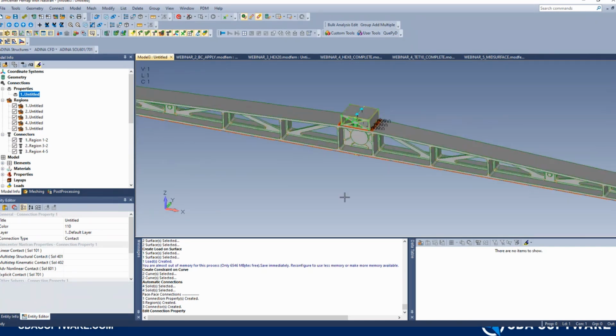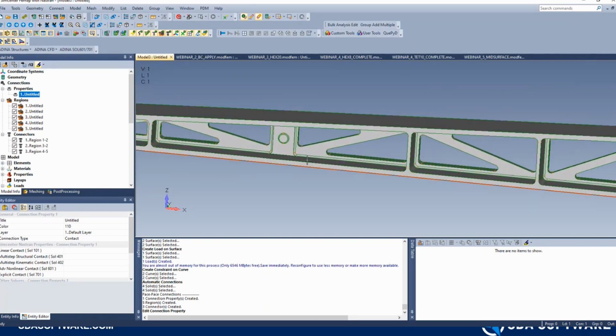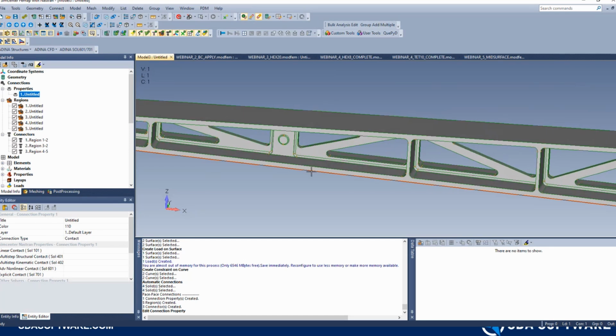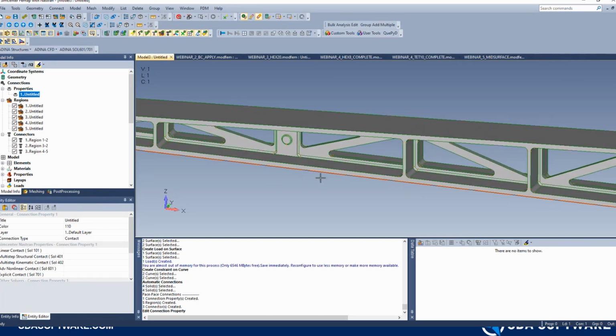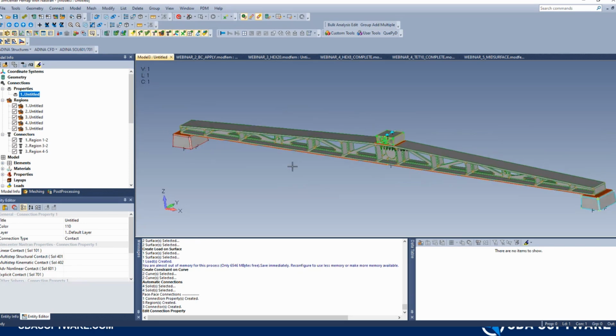Now, in the past, complex geometry like this could either only be tet meshed, which required many elements through the model, or if you wanted to hex mesh this, it would be hours of splitting the geometry, trying to make sure everything was extrudable and connected, which could take hours, if not days, even for simple geometry like this.